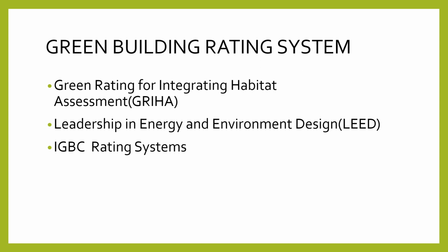Now, IGBC is the licensed authority for LEED certified green buildings in India. The 5 properties of LEED India are sustainable site development, water saving, energy saving, material selection, and indoor environmental quality.